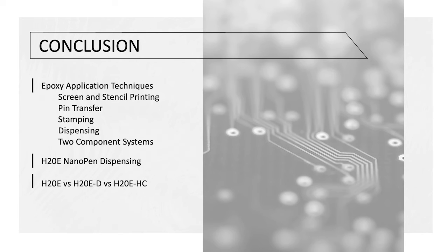When it comes to dispensing silver-filled conductive adhesives, a wide array of parameters lead to repeatable dots. Substrate flatness, needle type, and back pressure can all have an effect on dot repeatability. And even with similar epoxy variants, dispensing parameters need to be optimized.